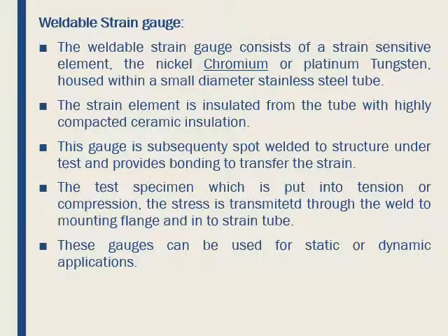For the semiconductor or photosensitive strain gauges, unlike other strain gauges, semiconductor strain gauges are based upon the piezoresistive effect of silicon or germanium and measure the change in resistance with the stress as opposed to strain.